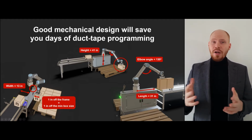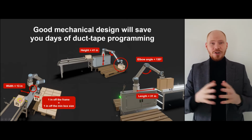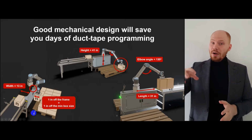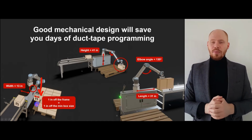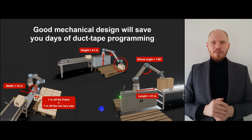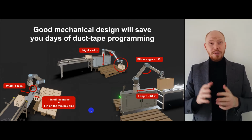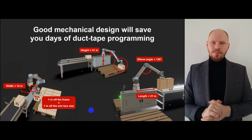Depending on the order in which you palletize boxes, your layout and box size can get a collision. You can get a collision between the wrist and the frame. This happens when the robot goes down to place the box or up to pick the next one. It is true that you can solve this with software, but logic becomes very complicated very quickly as soon as you have more than one palletizing layout. So to be on the safe side, just keep the width as small as possible.